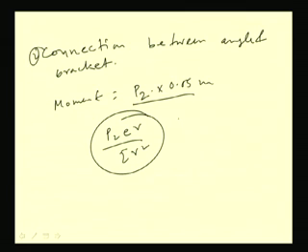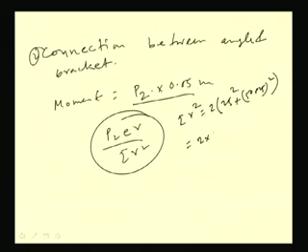So, let us first find out summation R square, because then we can find the values. Summation R square will become 2 into 25 square, the first one, and then 50 plus 25 square. These values are coming to 2 into 6250 millimeter square, and R will be the outermost, that means 50 plus 25, that means 75 millimeter.